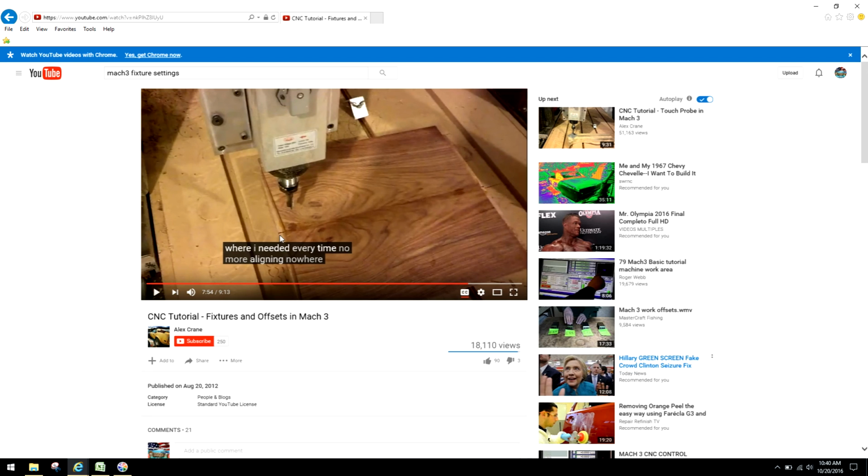Once again, if you made a jig, you could use as many offsets as you like. I think the idea of engraving in a table or the spoil board is an ingenious idea if you utilize it to its full extent. The guys that really truly understand machining would look at it as simplifying the process where they're getting as much accuracy as possible, and that's where the jigging comes in. Just bolting this down and holding it in place is not going to provide the accuracy you're probably looking for or should be looking for. I would do the jig. Once you make the jig, it's very simple to do. Put it in there, you're good to go.